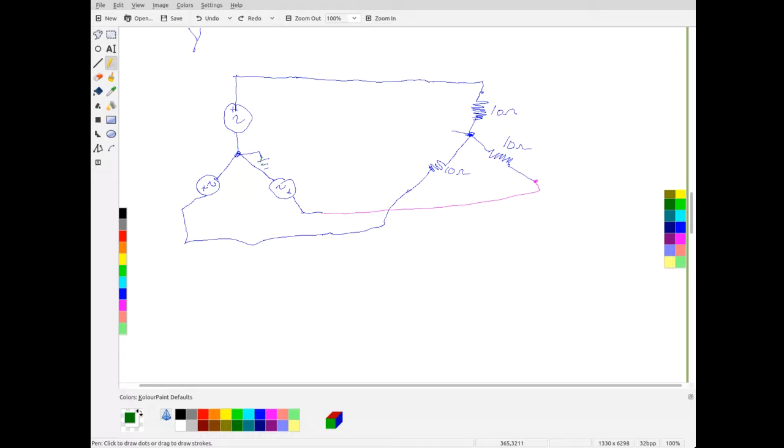All right. But looking at our power supplies here, I've basically got a generator to generate electricity. I've got one generator, and I've designed this generator such that it's got 3 different coils, and each are 120 degrees out of phase. So each is going to be a voltage. We'll call this E1, call this one E2, and call this one E3.